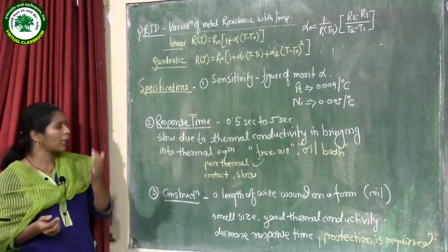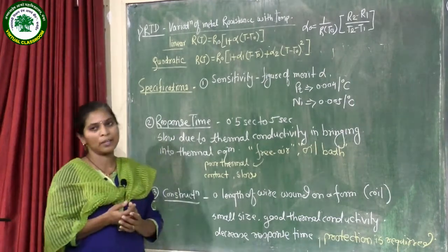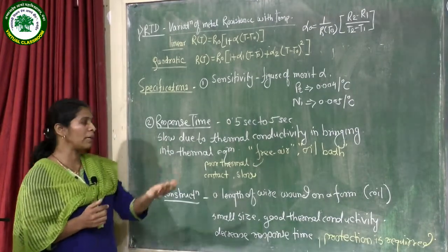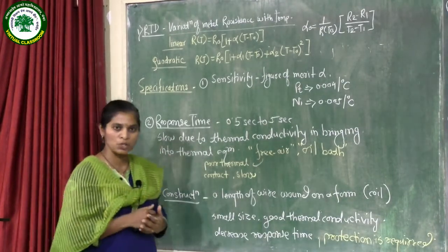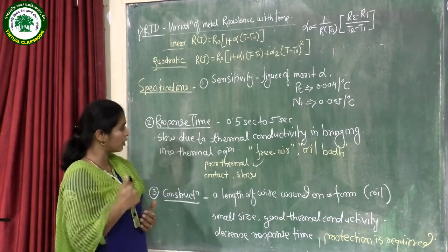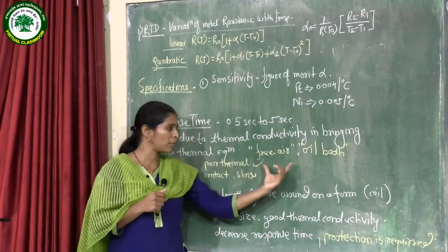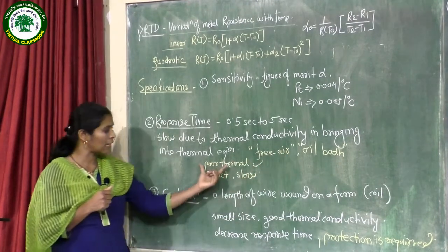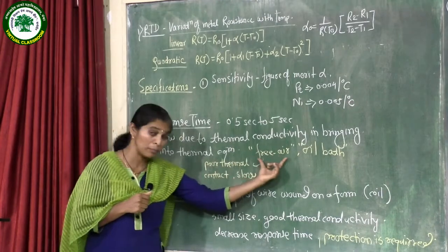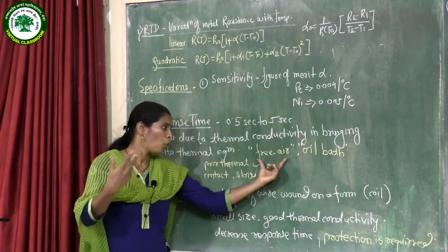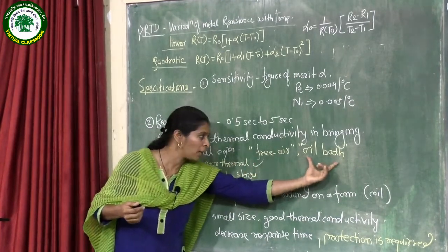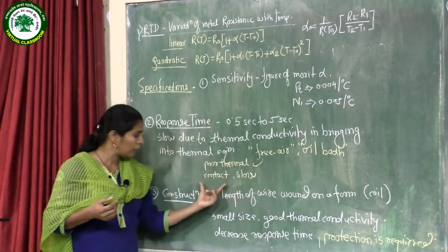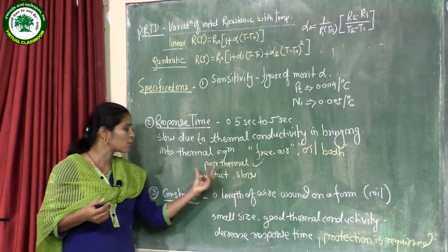Now over here two types of conditions are given. The RTD is a metal, and when this metal comes in contact with the unknown temperature, the medium is very important. As a result, when the response time is considered, when there is free air, we can say there is poor thermal contact because air is in between the unknown temperature and the RTD, while in the case of an oil bath there is good thermal contact. For free air it is slow because there is poor thermal contact.